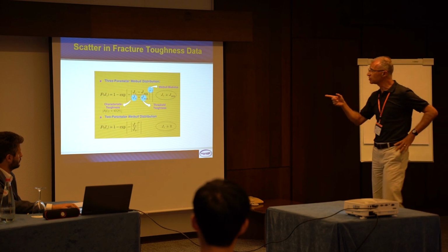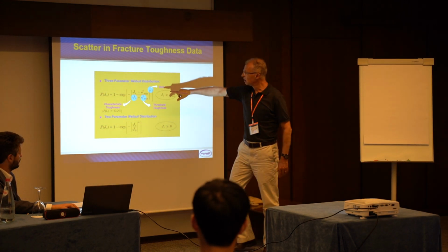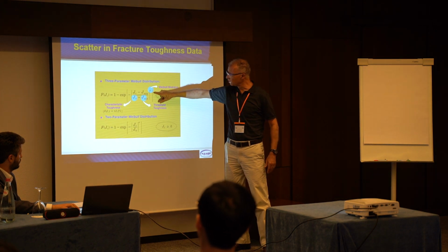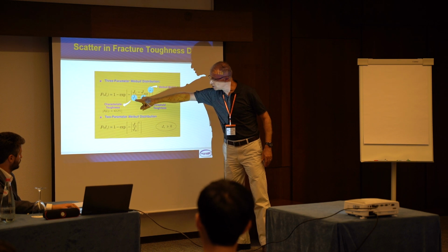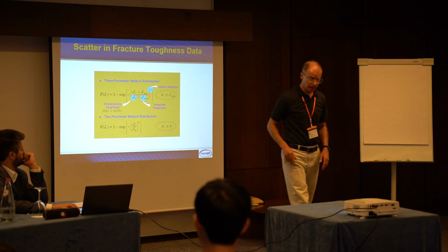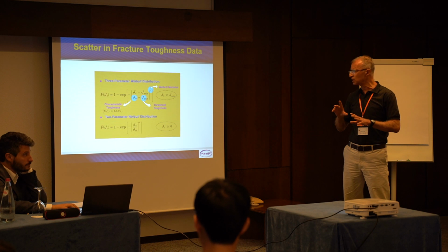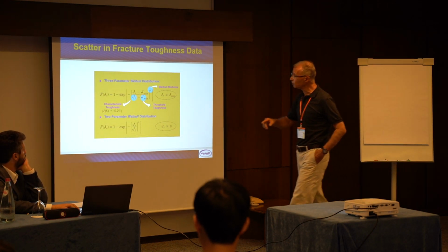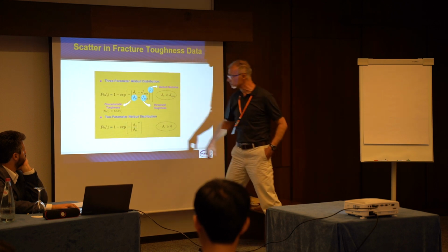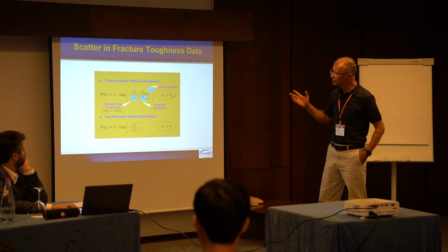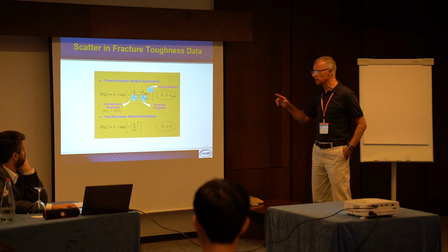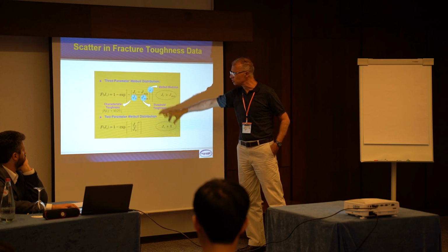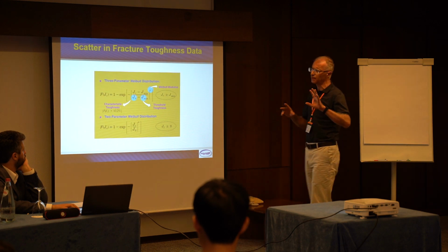Then we can see here that JC is the minimum toughness or the threshold, the Weibull modulus, and the minimum, and the J naught is also called the characteristic toughness, which is close to the average toughness. It's not, but it's close. It corresponds to a failure probability of 63.2%. In some cases, but not the master curve, we can just use the simple two-parameter Weibull distribution. So there is actually no difference between these two distributions, just a matter of fitting.